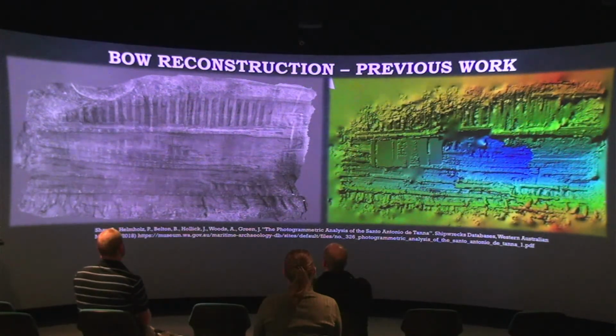While the reconstruction of the bow section was more successful, with the exception of the obvious errors seen in the DM on the right, all attempts to reconstruct the stern had failed using the traditional workflow. And you can see that flat spot is an alignment error. I think usually if two images are too close together, they'll treat all the features that are detected in those two images as a really strong match, and then they'll just say that's where those images are, and you won't get any depth from that section.